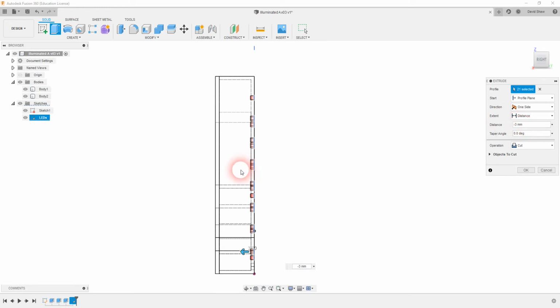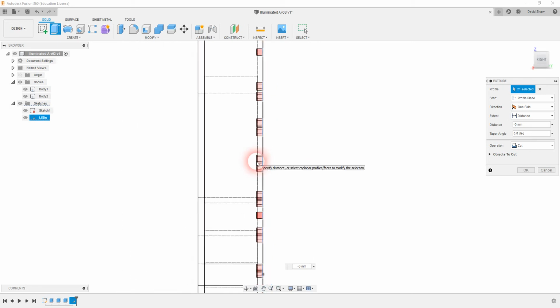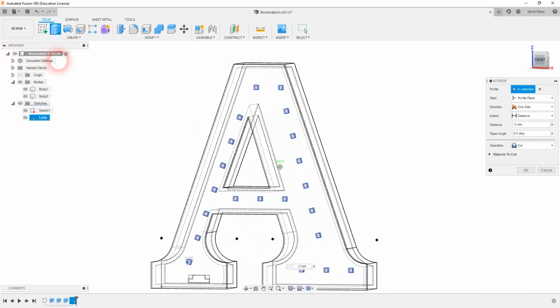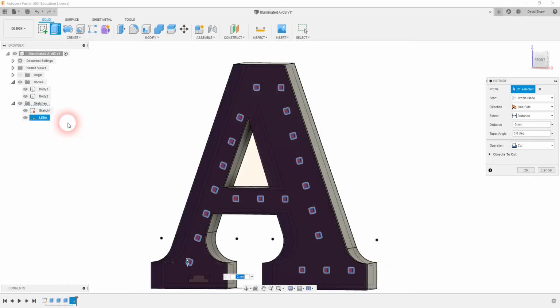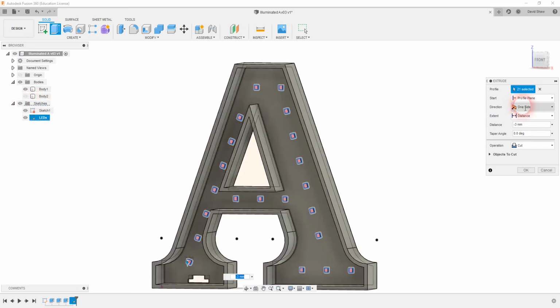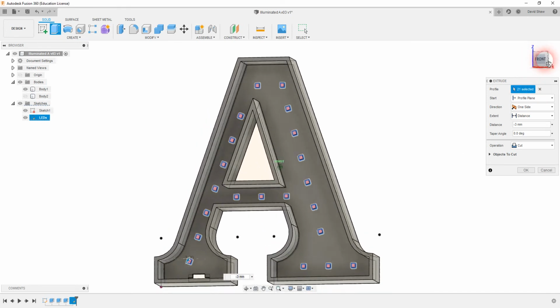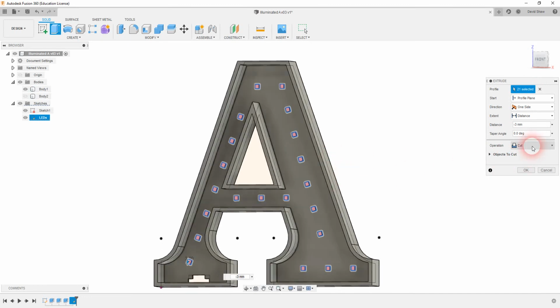Bit strange, but hopefully you can see here that these lights are just going to peek out by just 0.5 millimeter in front of the current 3D model. And in fact, if I come back to the TV screen here, Visual Style, and put this to shaded with visible edges only, and turn off the window, then now you can see how those little lights are just peeking out. And the final thing I need to do here, I can see they're pink, which means the computer thinks I want to cut them out.